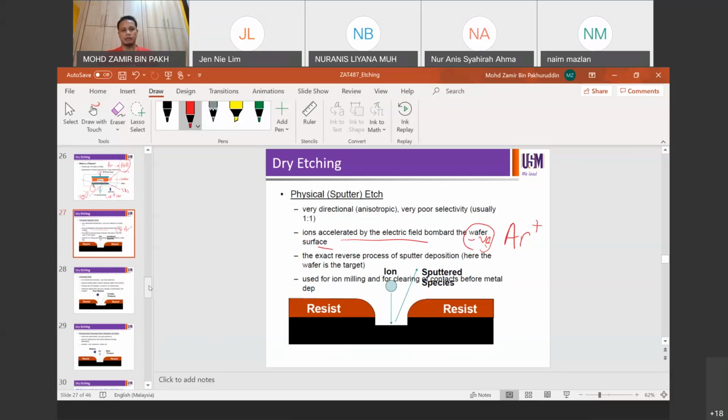So in this case, ions are removing the exposed area, so the areas will be etched. Originally, perhaps all of this would be black. Now it has been removed. Originally, maybe all these are black, assuming the black one is silicon, right? So then you're going to remove material, you're going to drill the drain or trench. Sometimes we call this a trench. The hole, trench.